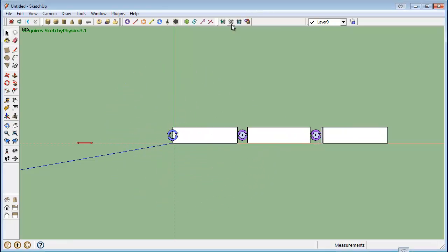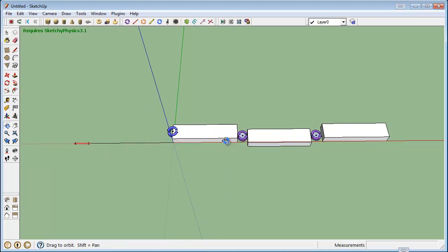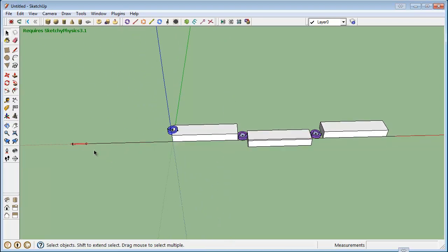And the way it works is that we have these three blocks here. One of them is attached to this slider, so it will slide back and forth, whereas one block here is attached to the motor. So the motor is actually driving the whole thing. Between the two of them you have a linker arm, and it's attached to both by means of these two hinges, so the hinges are passive. The motor provides all of the driving force for the piston engine.